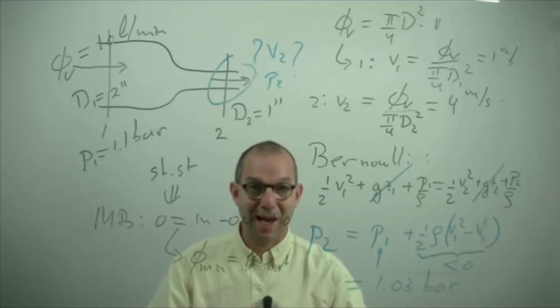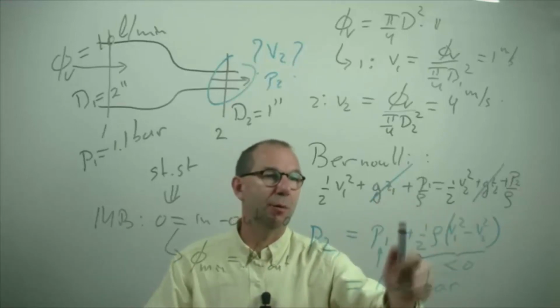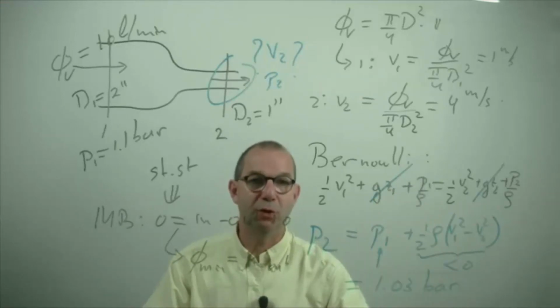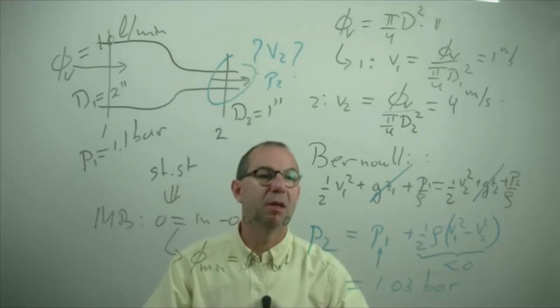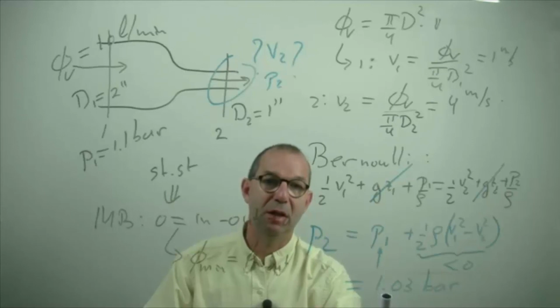Nothing is adding energy to the system, so the water takes it from itself. It cannot take it from the height. All it can do is convert part of its pressure energy into kinetic energy. And thus it has less pressure energy left when it's flowing through the narrowing.